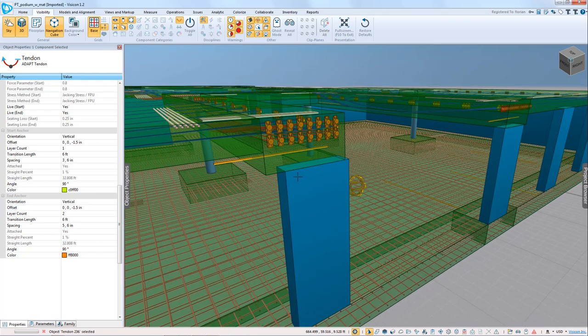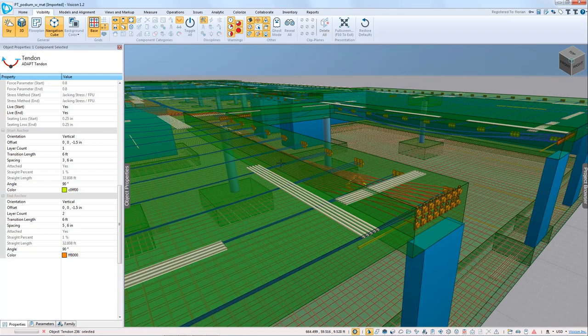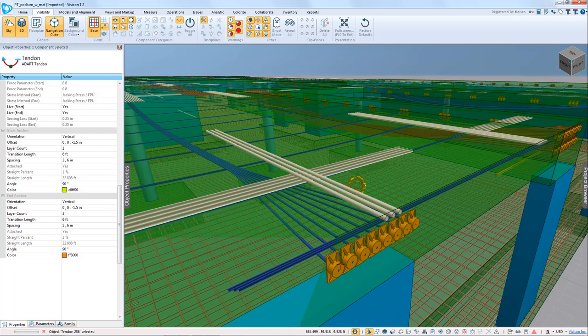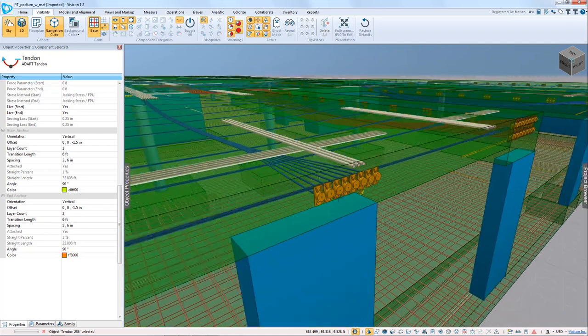It looks to me like there'll be enough room to accommodate whatever reinforcement will finally be there. Again, the purpose of this is to give you an order of magnitude degree of confidence that the number of tendon anchors you're proposing may be able to work, knowing how much rebar you're also designing at that location.